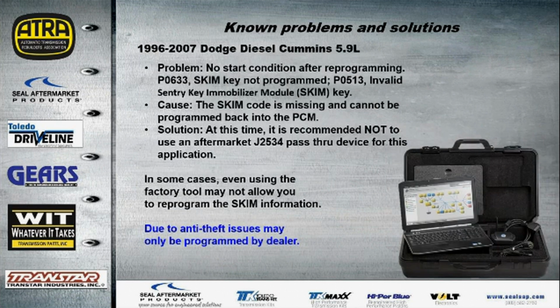1996 to 2007 Dodge Cummins diesel 5.9 liter. No start condition after reprogramming. You can reprogram these, but after you reprogram them, a lot of times it renders the whole vehicle useless. It cannot start up. And basically, we don't have the ability to rewrite back into the Cummins modules.